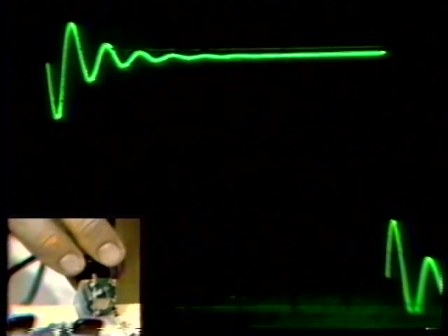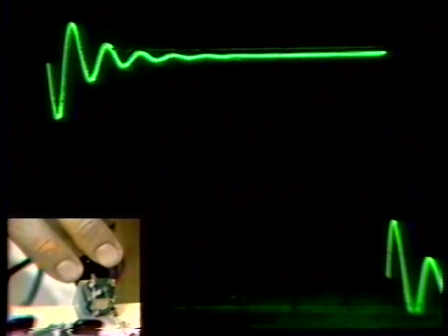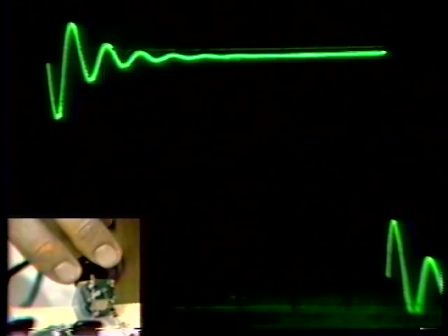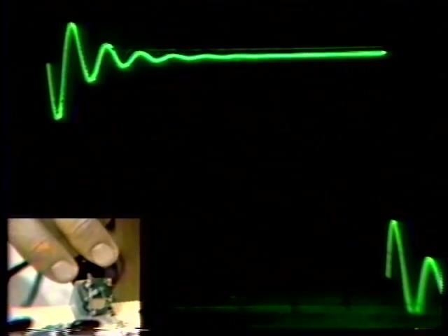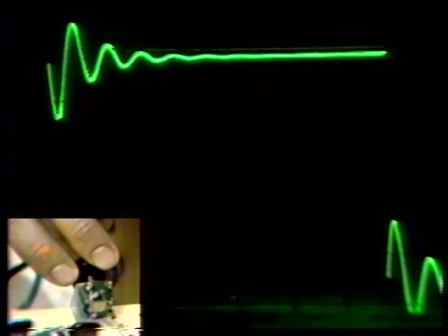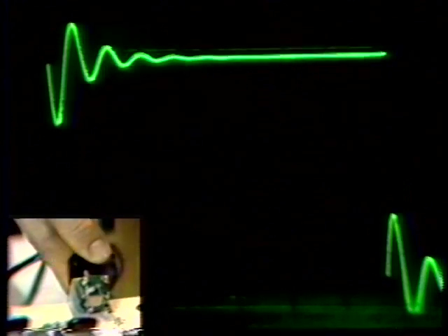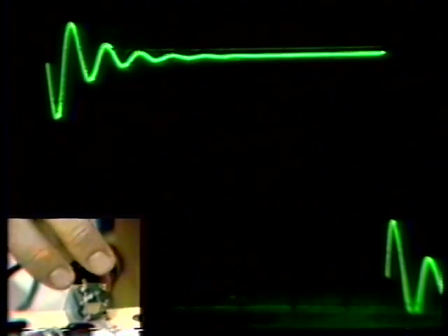From here on in, the frequency of the residual component would not increase very much because, of course, the complex conjugate pole pair would be simply getting closer and closer to the zeros. The imaginary component would not change very much at all from here on. So it's a system that has a rather interesting step response.